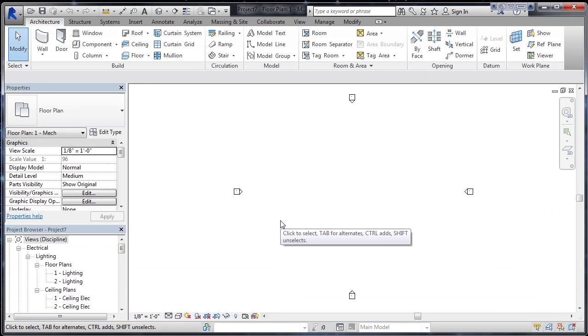This will now create a new Revit project with information from the Systems-Default template. And it loads a variety of things into the project. Now, depending on your processor speed and the amount of RAM, this may go relatively quickly, like mine did, or it may take a little time to load because there are a lot of things being put into the project. Well, if we look in the project browser in the lower left, you're going to see a lot of views that are already created. And levels are created as well.